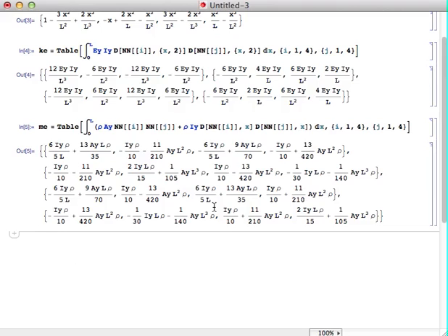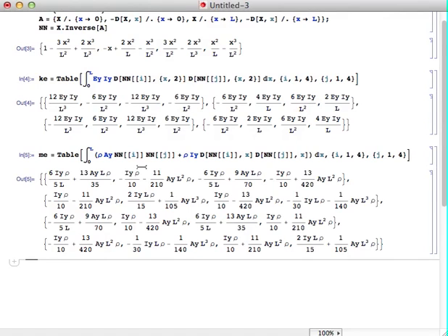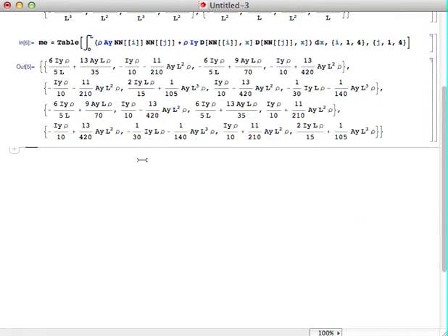I have a quick question. Go ahead. So up there where you have the stiffness matrix, you don't have the derivatives of the shape function. I mean, on the screencast view, but on the board, it's just EI, Ni, and J. For the stiffness matrix? Yeah. Oh, okay, yeah, that was a mistake. It should be the second derivative of the shape functions. I just miscopied it from my notes. But like I said, that's exactly the same stiffness matrix as we previously had for the beam. So go ahead and correct that. Sorry. Good catch.